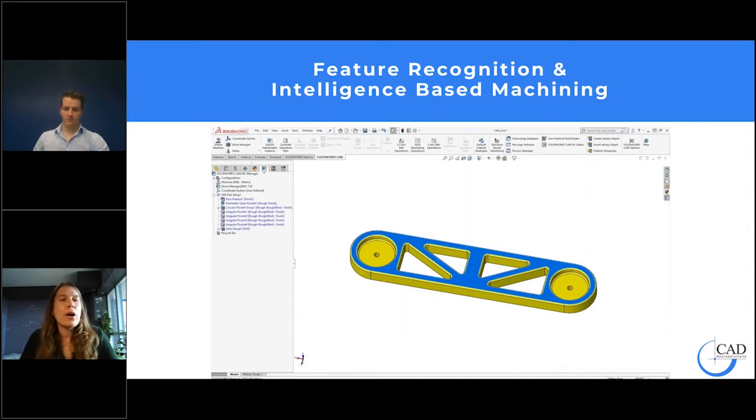So we can have the software automatically define things like depth of cut, our roughing strategy, what kind of lead in, lead out we want to apply, and NC parameters like our clearance plane and our feed plane, all with the click of a button. There's no need to change these settings over and over as you program each new part. You can really teach the software how you want to use it as you use it by saving back all of your changes to the technology database.